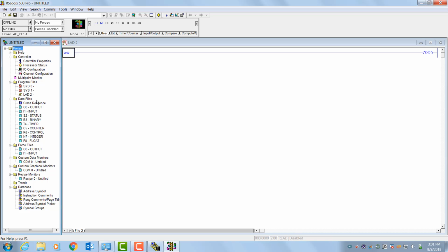Over on the left, we have a file window. When you're over here, you can see the layout of the software and the different parts of the processor that it sends and receives data to and from. We'll get into a few of these files as we go through the course. You'll notice up at the top here, we have this little window with the ladder, because these are ladder programs, and nothing's moving. When we get this connected up and we're talking to the processor, we'll see this moving, and we'll actually be able to know that we are connected and we're online with our PLC.